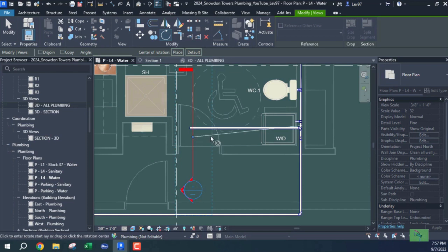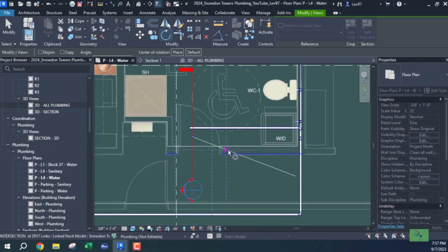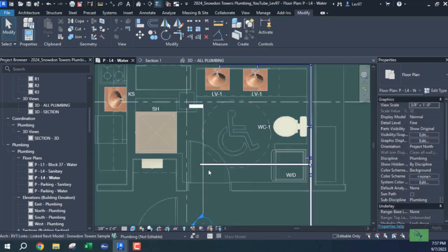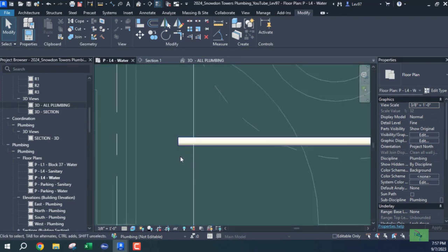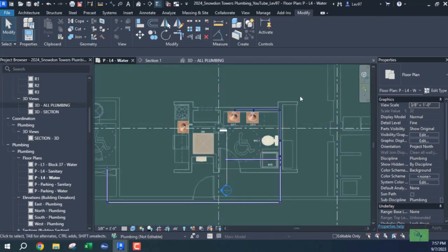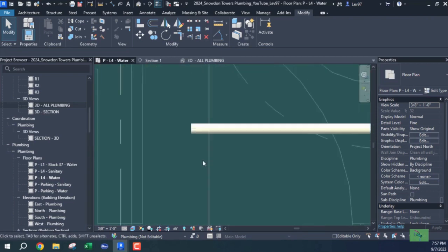I don't know what you call these things. These nearest to all of these snap modes, all of this snap, you see all those dash lines? You don't want that. You want it to be perpendicular or in 90-degree modes. So you don't want to see those lines. So when you know you're going to rotate, you want to get in close, because I'm going to concentrate in this area anyway. I'm not going to concentrate over here or over there. I'm going to concentrate back in here.